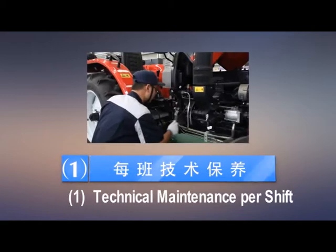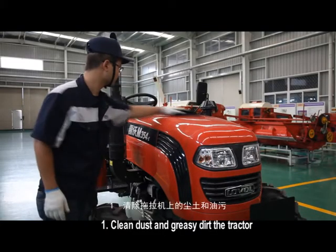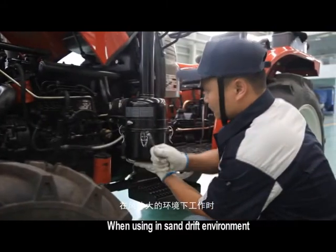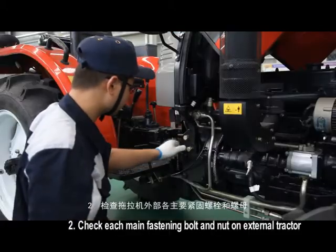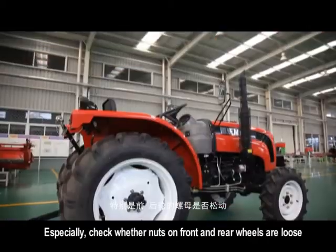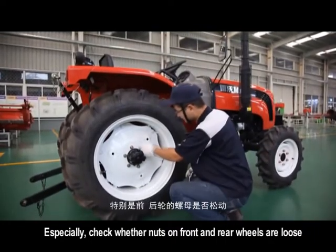1. Technical maintenance per shift. 1. Clean dust and greasy dirt off the tractor. When using in a sand drift environment, clean the air filter. 2. Check each main fastening bolt and nut on the external tractor. Especially, check whether nuts on front and rear wheels are loose.